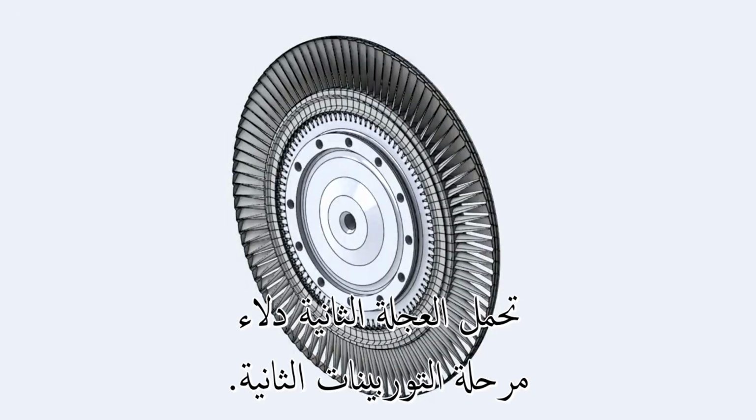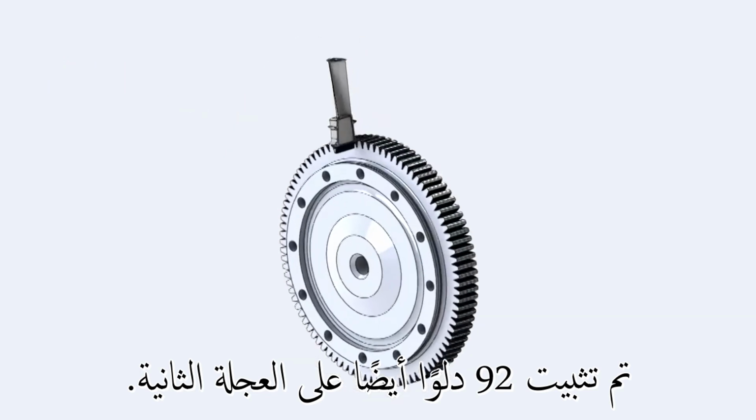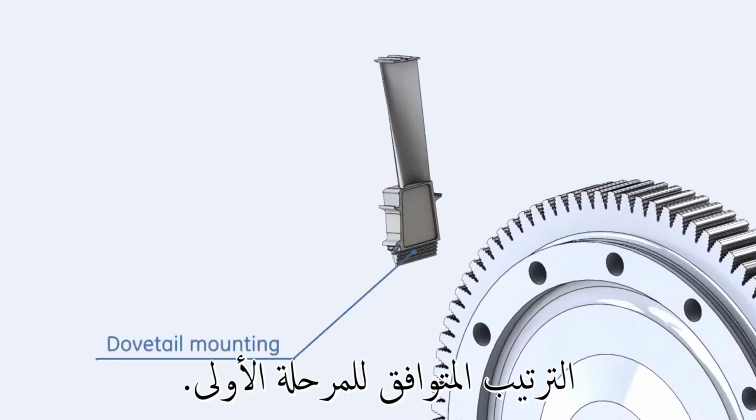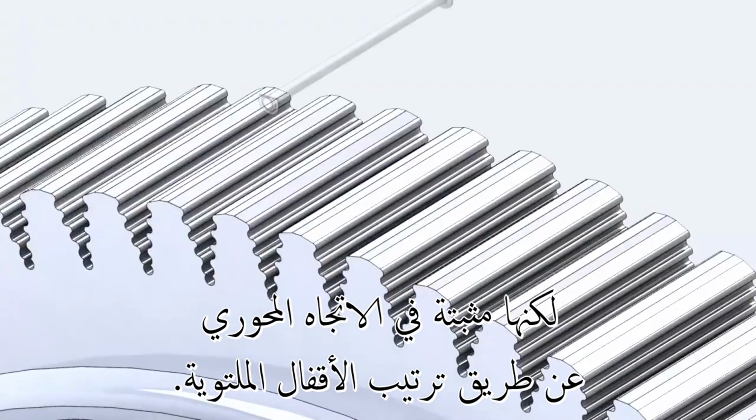The second wheel carries the buckets of the second turbine stage. 92 buckets are also installed on the second wheel. Buckets are attached to the wheel by the same dovetail arrangement as the first stage, but they are held in the axial direction by a twist locks arrangement.